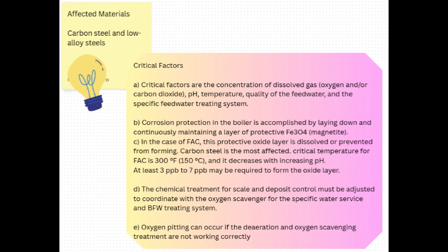Okay, so that's oxygen, nasty little pits. Now, how does that compare to the second chemical threat, carbon dioxide? The CO2 is a different beast. It dissolves in water, forms carbonic acid. Right. And this attack, carbonic acid corrosion, it usually looks like smooth erosion, kind of general thinning. Smoother than pitting. Yeah, but it can also cause grooving, especially in high flow areas, little channels carved in the pipe wall. And this is a really common problem, especially in the condensate return system.